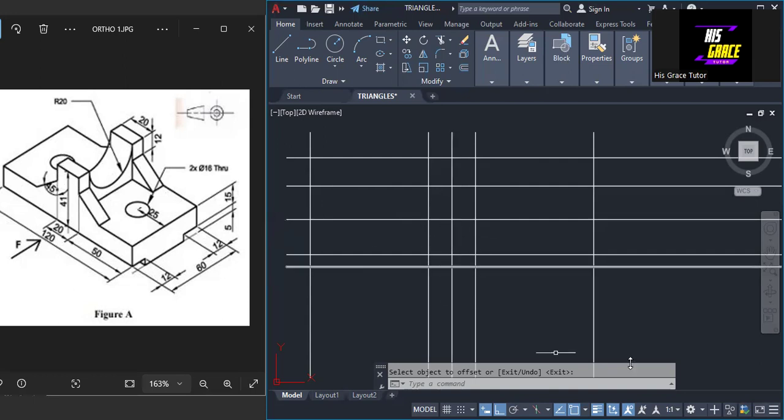So how do we do that? I will turn off the auto mode and then take the line. I will draw from here, 45 from 180, which will be around 135. So I'm going to input an angle. Press the tab key on the keyboard and give it 135. Press the enter key. So that's it, we have the line.